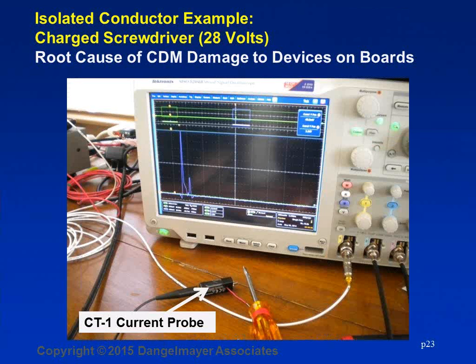The test that was done was actually, he would charge the board and the component up together, and then he would discharge to the component. So it would be simulating, say you have a charged board and then you reach in with a soldering iron to fix a solder joint or something on the board. That would be kind of a simulation of what you're seeing there.